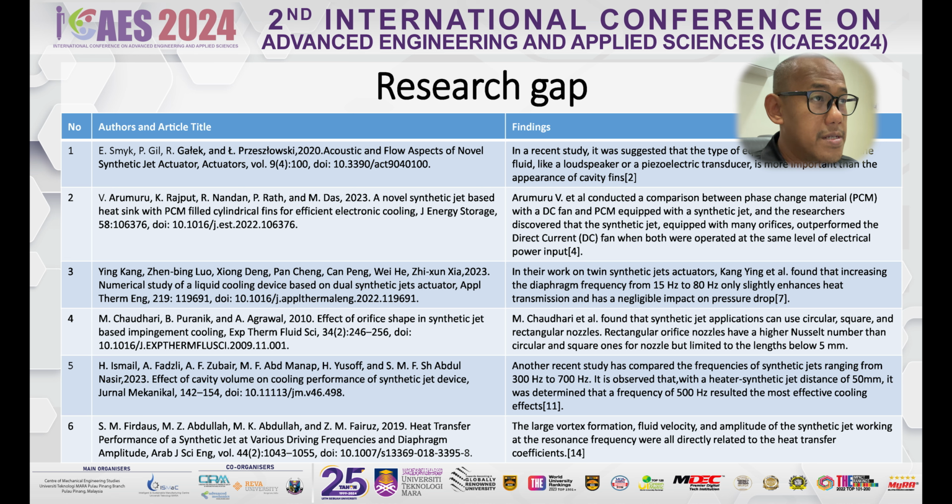In recent studies, it was suggested that the type of equipment used to move the fluid, like a loudspeaker or piezoelectric transducer, is more important than the appearance of cavity fins. Other notable studies also mentioned frequencies of synthetic jets ranging from 300 Hz to 700 Hz.